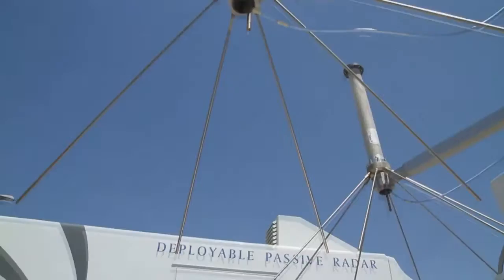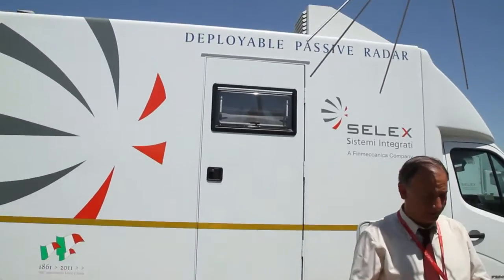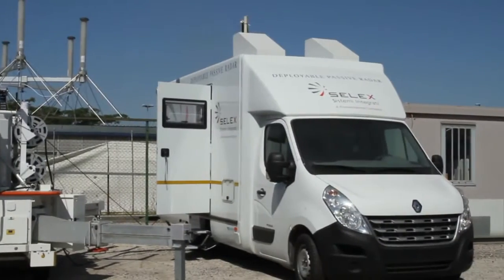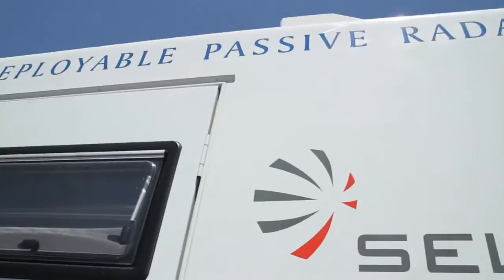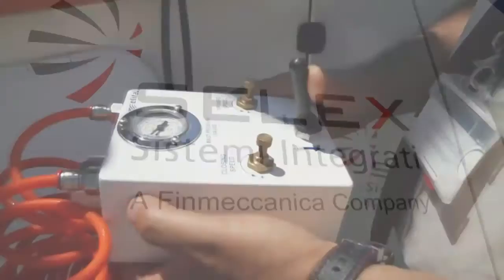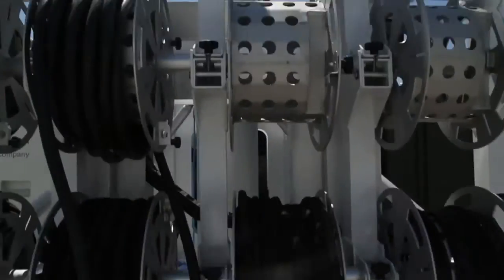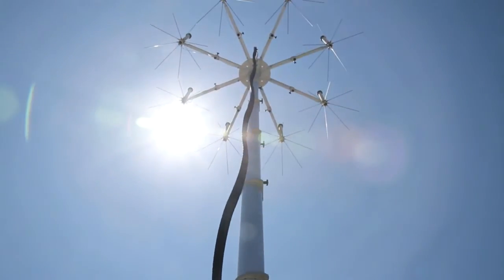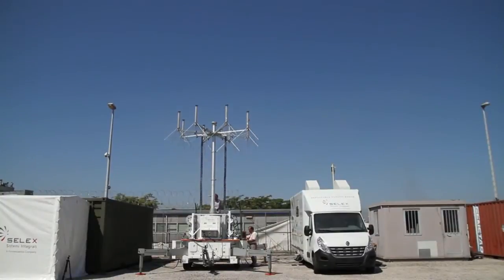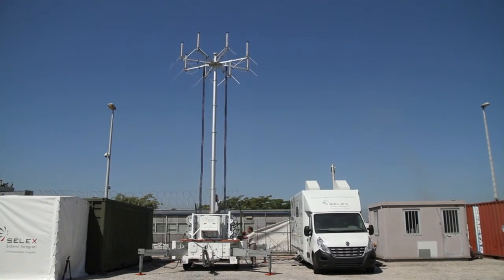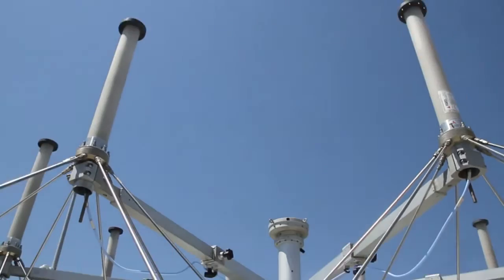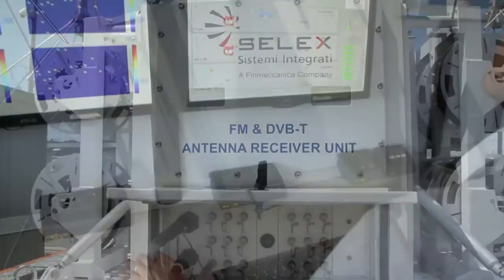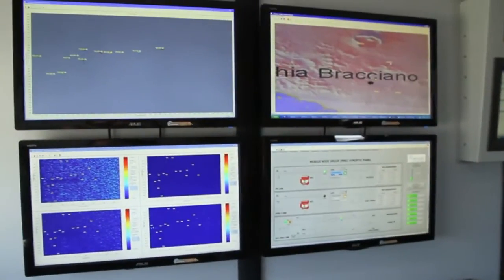My name is Riccardo Mancinelli. At the moment, I'm in charge as program manager, technical manager of the passive radar system project. Our main goal was to have processing as fast as possible. And digital down conversion, multiple digital down conversion, because we tune our system simultaneously to a certain number of stations in order to have a good target detection and localization.